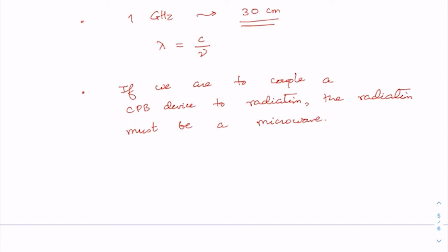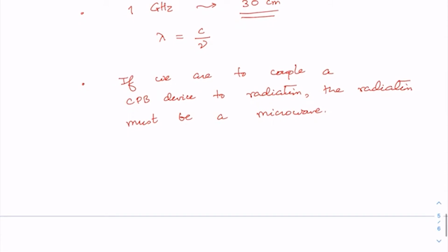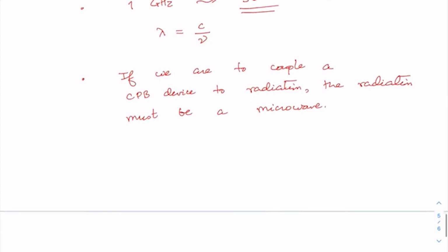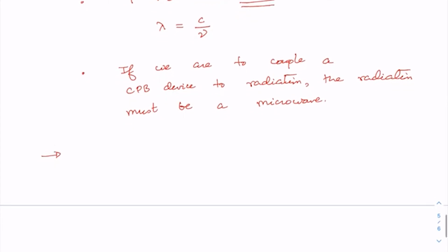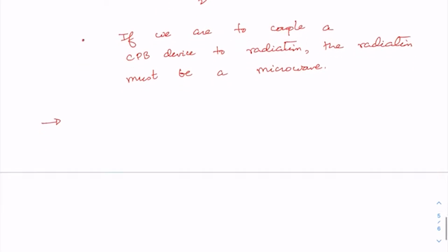Okay, before I go further, let me quickly give you some important information about the Cooper pair box. First of all, what is the circuit representation of a Cooper pair box? A Cooper pair box or a charge qubit can be depicted by this kind of circuit. You have this gate capacitance here, and then you have this Josephson junction. This big cross denotes the Josephson junction.